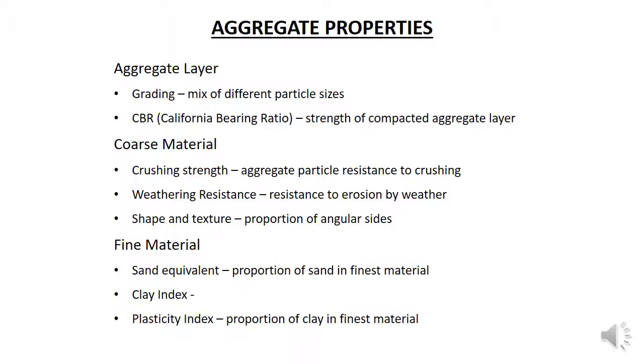The sub-base and base course in most flexible roads are unbound aggregate layers. Aggregate is a mix of separate gravel and sand particles. Unbound means that the aggregate particles are not cemented or otherwise stuck together. Unbound aggregate layers rely on the interlocking of the various aggregate particles for their strength.